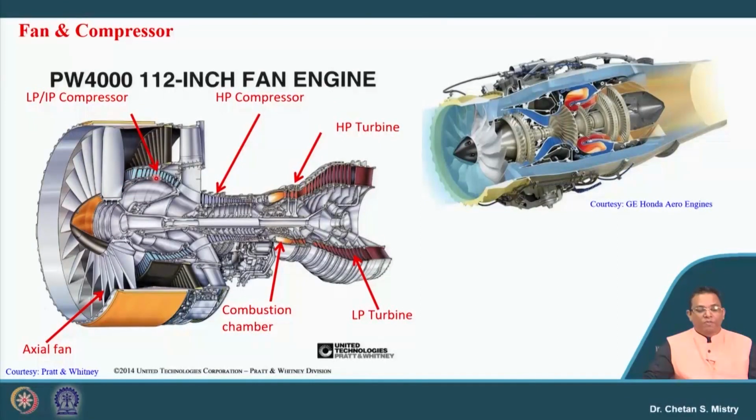Now, downside if you look at, these are also representing the compressor. This is defined as the LP compressor or low pressure compressor. In some companies and some literature they use the terminology intermediate pressure compressor. Next, what we have is also a compressor, called the high pressure compressor, the HP compressor. So, the terminology that we are introducing here is LP and HP.